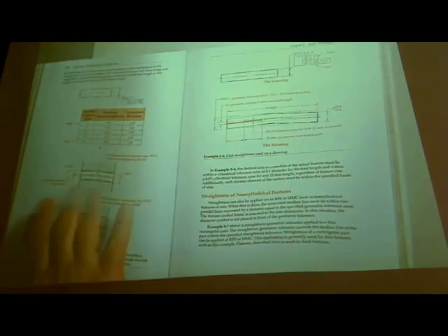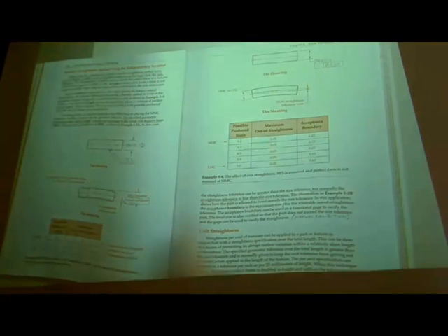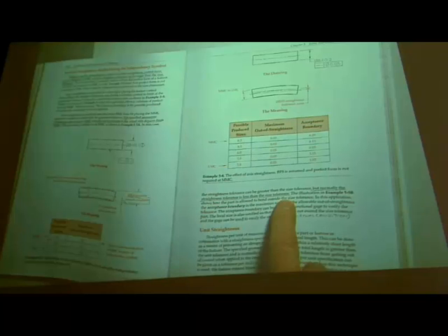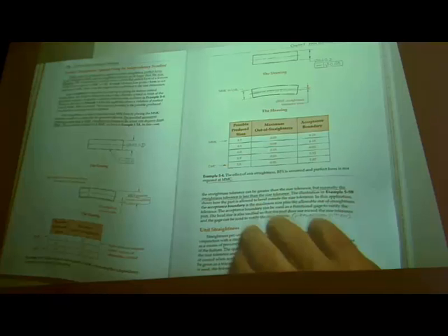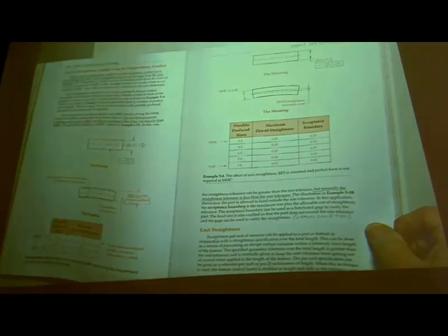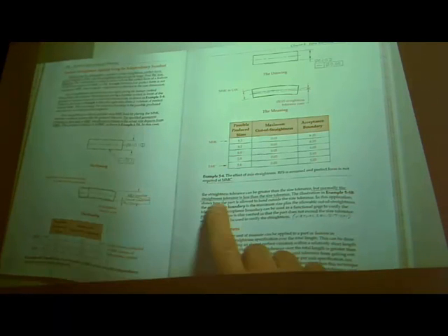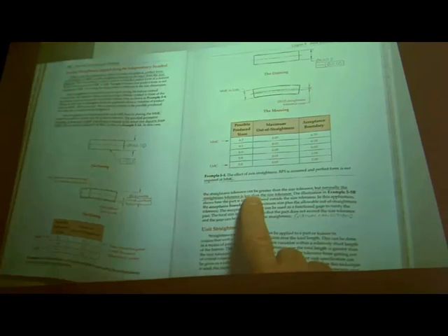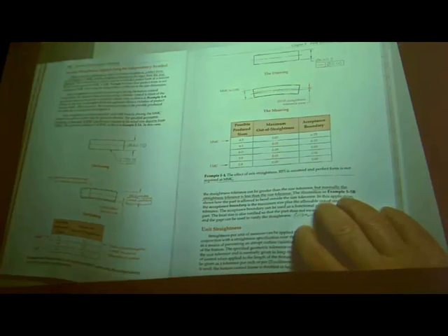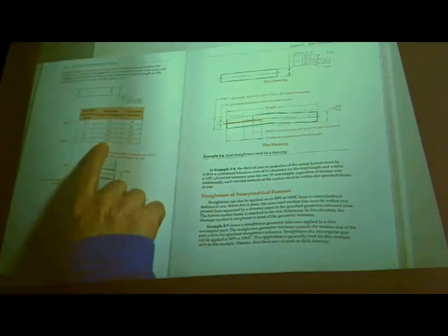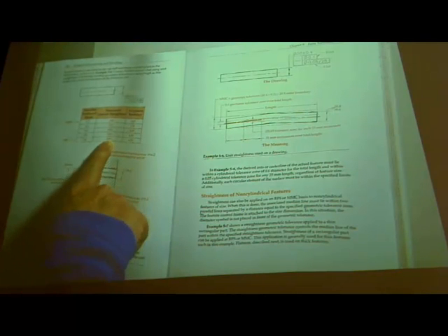All right, normally, as it states here, normally the straightness tolerance is less than the size tolerance. Okay, so in this case, the straightness tolerance can be greater than the size tolerance. Now they're talking about, you know, the calculated straightness tolerance.